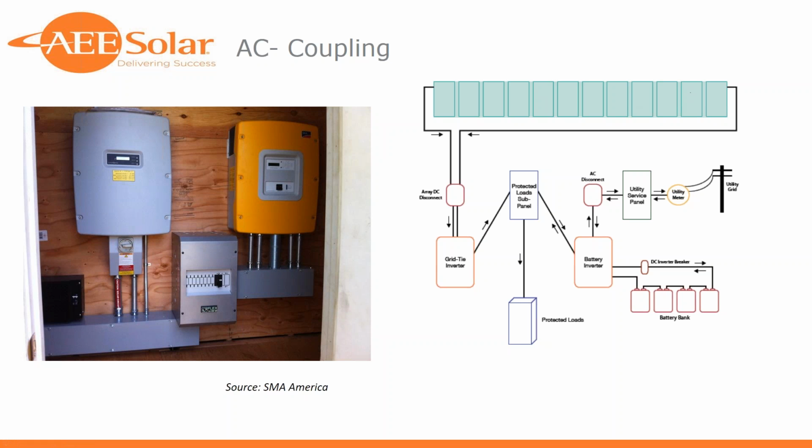So right there, one of the first original benefits of AC coupling was being able to introduce longer strings. In using a grid-tied inverter, you're moving up to a 600-volt DC bus on the array. Previously, and this goes back to pre-2012, I suppose, the charge controllers we used in residential solar plus storage were typically 150-volt bus. So you're looking at strings usually of 3, and you'd parallel those strings onto a charge controller. And if you needed more than, say, 4,000 or 5,000 watts of array, you'd have multiple charge controllers that you'd then parallel onto an inverter charger. So right now, we clearly see one of the benefits, which is longer strings.